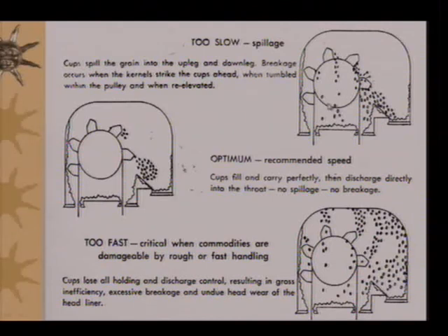And if you are operating your machinery at too fast a pace, if the speed is too much, then what happens here? Cups lose all holding and discharge control, see here, and material goes helter-skelter all through, and then again you find excessive breakage and undue head wear of the head liner. But if the recommended speed is used, you will find cups fill and carry perfectly, then discharge directly into the throat, no spillage, no breakage. So this should be kept in mind, that we must operate our bucket elevators at an optimum speed